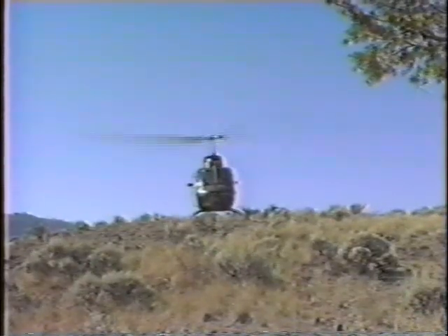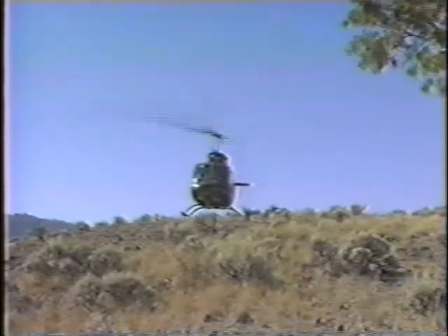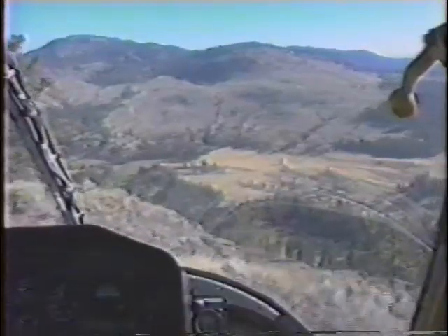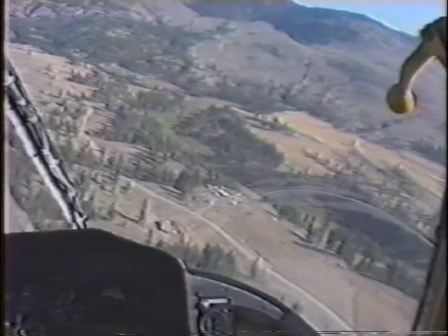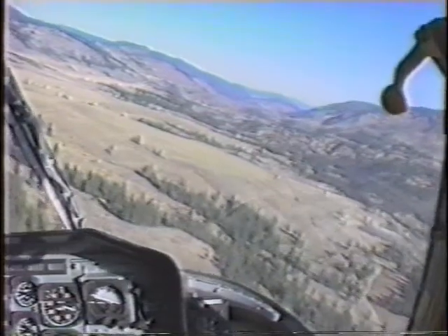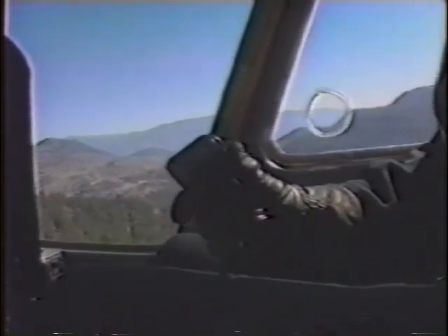When you're satisfied you've assessed the takeoff to the best of your ability, slowly ease the aircraft into a low hover, check the center of gravity and power requirements. If it's all clear, slowly ease your cyclic into forward flight following the contour. In other words, slide off the mountain. This contour takeoff uses less power, maintains ground effect into translational lift, uses a smooth application of power with no droop, and keeps you from spilling the disc because it stays pretty much flat. Again, it's safer and more effective.